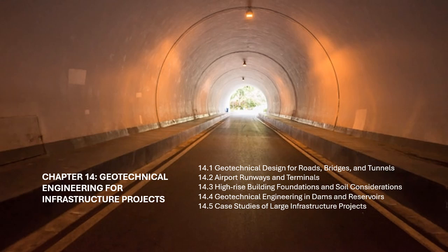Shallow foundations. Shallow foundations, such as spread footings or mat foundations, are used in areas with strong, stable soils that can bear the weight of a high-rise building without excessive settlement. A mat foundation, also known as a raft foundation, is often used when the building is large or the soil is not uniform, as it spreads the load across a wide area. Mat foundation.